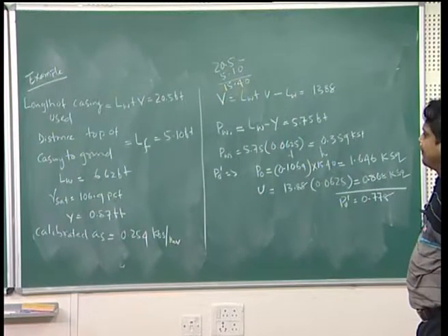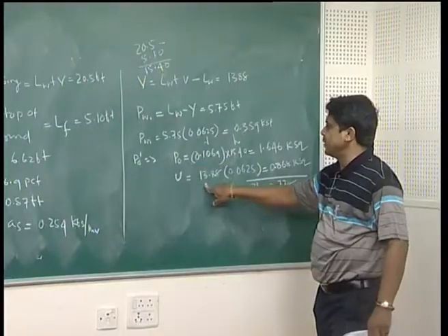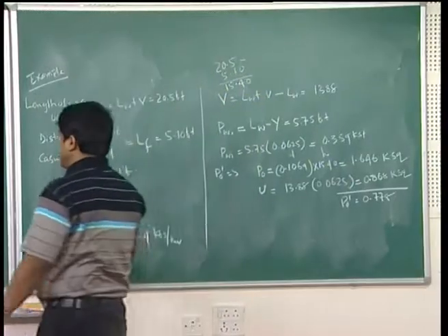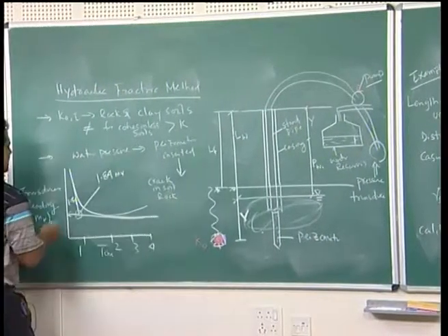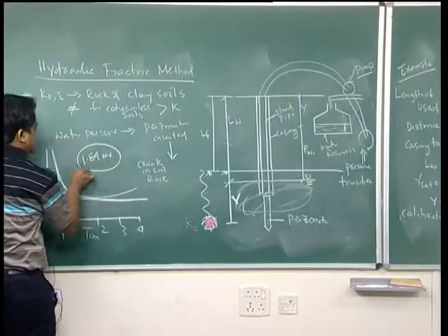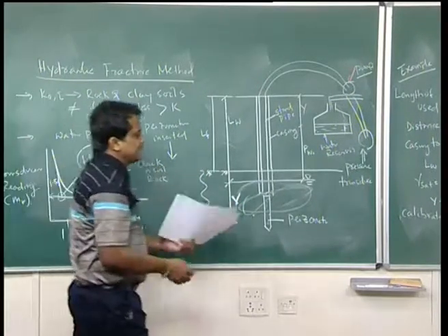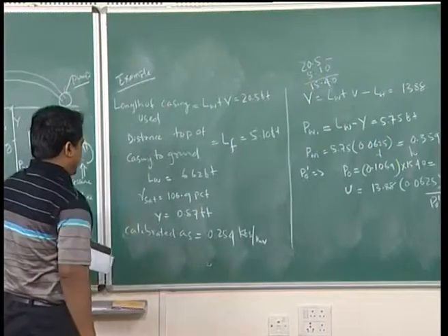This is your effective overburden pressure. I calculate total minus pore water pressure. So, this is effective. With this pressure transducer calibration, it is observed that the fracture point observed is 1.84 mV. The calibration is given as 0.254 kips per square feet per mV.